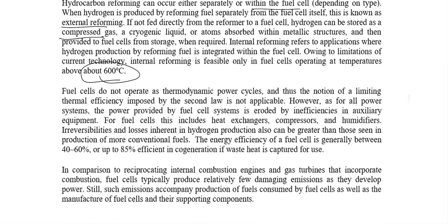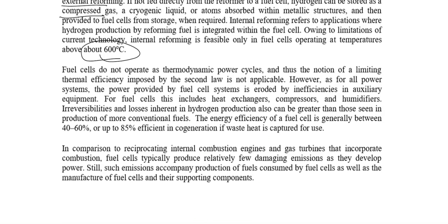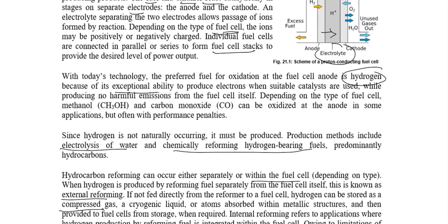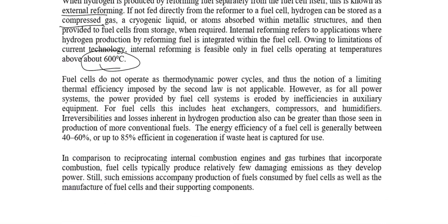As we can say, a fuel cell does not operate on any thermodynamic cycle, or have any thermodynamic component, for example, heat exchanger, compressor, humidifier, turbine, and no auxiliaries, no irreversibilities. So obviously, it does not work under the limitation of the second law of thermodynamics, or, I would say, it does not come under the Carnot limitation.